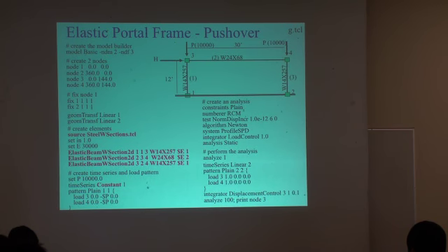So the first time we come in here, the time of the domain is going to be 0.1, okay? If we analyze 1, time equals 0.1, if we have load control with 0.1. If I analyze 1 again, the time now will be 0.2. For right now, ignore the time step. So if we analyze one at a time, it increments by 0.1 every time step, because the increment is 0.1.